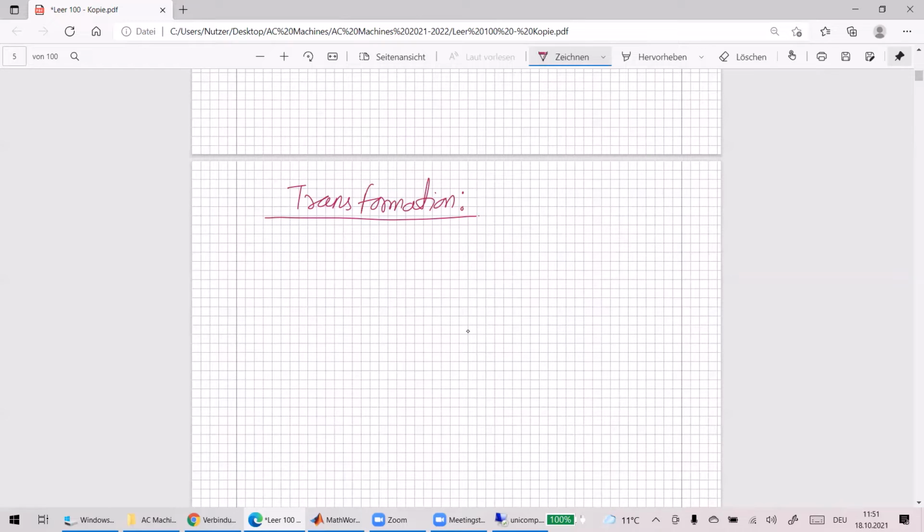So people used resonant controllers in three phases, with three resonant controllers, one for each phase. That's not really good, I would say, especially when we look at passivity plots or the dynamic plots. It's a little bit more complicated. So let's say we have three controllers for three phases.